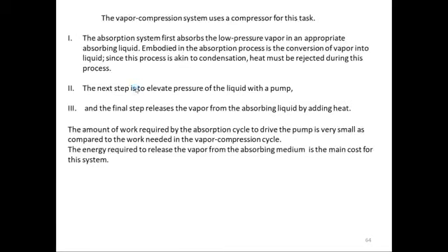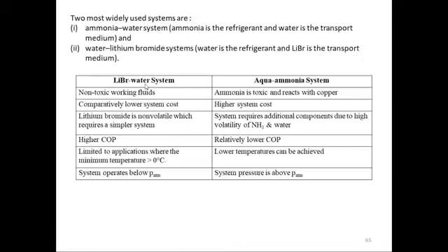So in the lithium bromide water system and the aqua ammonia system, if we do a comparison between these two: in the lithium bromide water system, water is the refrigerant and lithium bromide is the transport medium, and in the ammonia water system, ammonia is the refrigerant and water is the transport medium. So with lithium bromide, water is a non-toxic working fluid. Ammonia is toxic and reacts with copper. Comparatively lower system cost for lithium bromide.